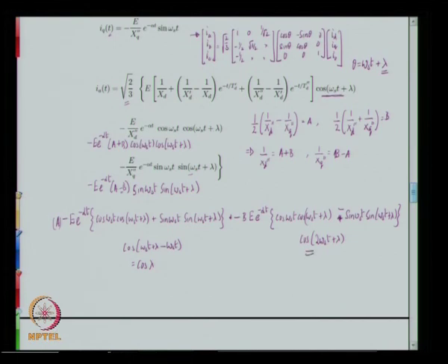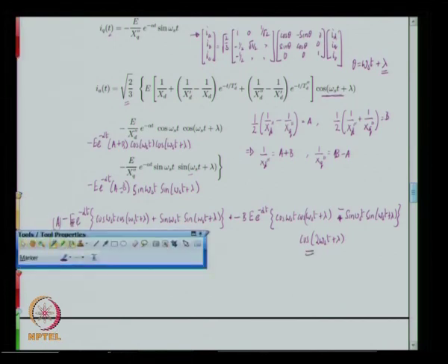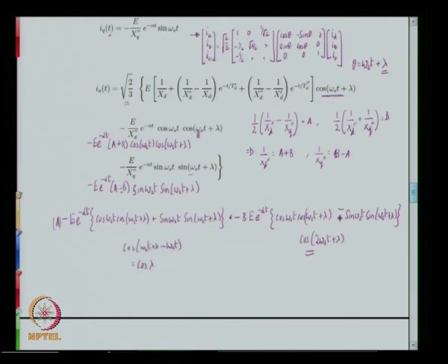So, if you look at these two terms together, they then can be separated into two terms. One involving just cos lambda, this is not a sinusoidally varying term, whereas this term is sinusoidally varying, but at a frequency 2 times omega s, and therefore we get an expression for Ia of t in this manner.